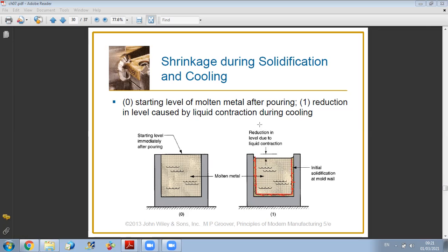In general, the shrinkage will take place in the dimension perpendicular to the cross section. Why? Because of the presence of the riser, the base area will be covered continuously, and you will not have a reduction in volume from this side, because the riser will continue to supply metal in a way to maintain the constant base area.